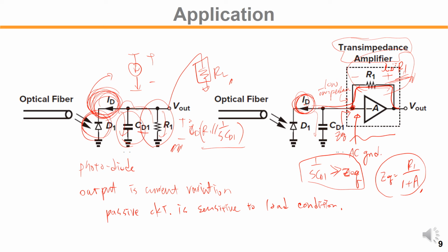So this transimpedance amplifier is suitable for what? If the input is a current input, like a photodiode. The photodiode is the current input. The current source input has the characteristic of large output impedance, right? So the input signal is current rather than voltage. Okay.